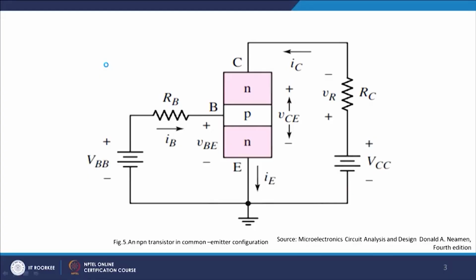And that is what you can see on this diagram here. I will make it a much better diagram from the point of view of understanding, which is this one, right. So, I have an NPN transistor, I have a BJT, and I have my base emitter junction forward biased, and my collector base junction reverse biased, this one, right. So, let me just draw for you from the circuit point of view, and let us see how the common emitter configuration works in this case.